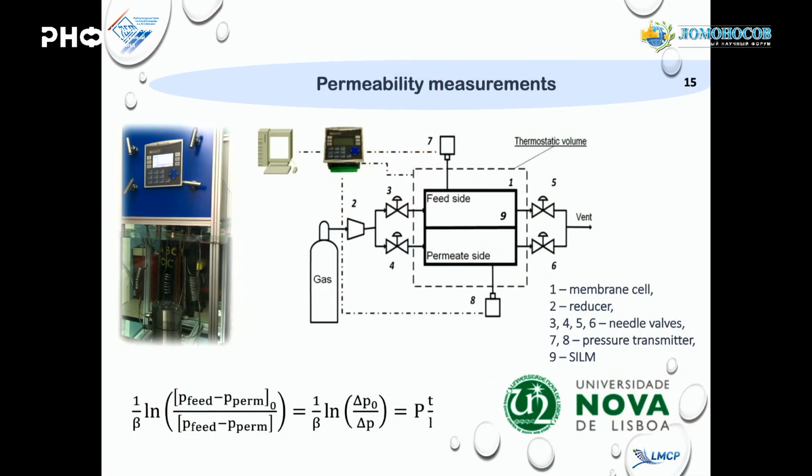And then we can easily make the permeability measurements, to check the separation ability of the membrane. This is also quite simple equipment. When I worked at Lisbon University, with Professor Crespo, they showed me this really simple equipment. We have an upper side and a lower side, chambers separated by the membrane. You put the gas in both sides, vacuumize a little bit down from atmospheric pressure, and then you just wait and obtain the numbers really easily.